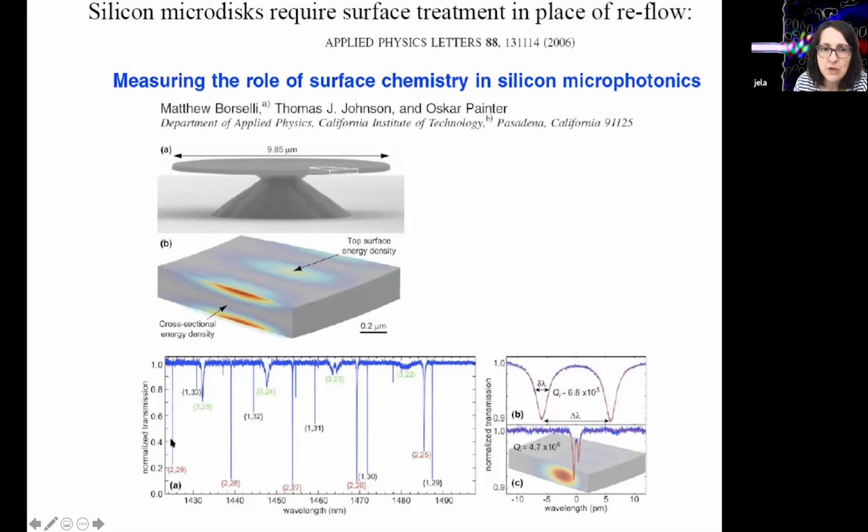So whenever you hit a resonance of the disk, you would have a drop in transmission through the fiber, which is coming from the fact that you are exciting a mode of the microdisk. Once you couple to the microdisk, that could re-radiate somewhere else into some radiative channels, or there may be another waveguide to which you are dropping, as we'll see in a moment in different configurations, but it would not be transmitted down the fiber, right? So that's why there are these drops.